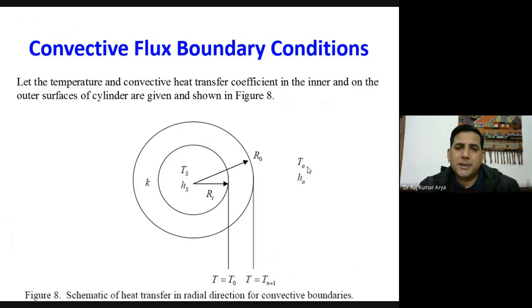So let's say this is a typical case of heat transfer through a cylinder by convective heating, or maybe cooling, depending on what you need. But outside of that, you have the atmosphere, and from there you don't want any sort of interference. Let's say the purpose is just to transfer heat from steam to a fluid flowing inside the annular space. For that particular case, what do you need? You don't need any loss of heat from the outer cylinder to the atmosphere.